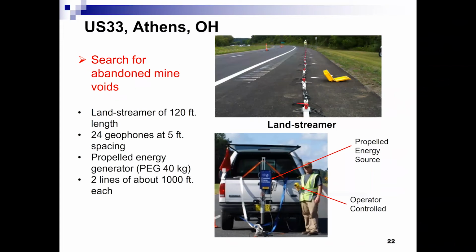So here we use a land streamer geophone. Simply, we just put the geophone on top of the metal tripod, so we don't have to couple the geophone into the pavement material. We tie all 24 geophones together so that we can move quickly along the road.